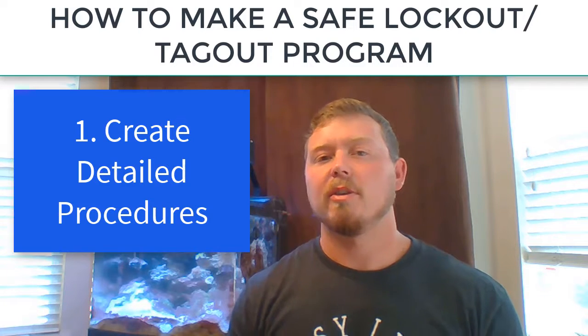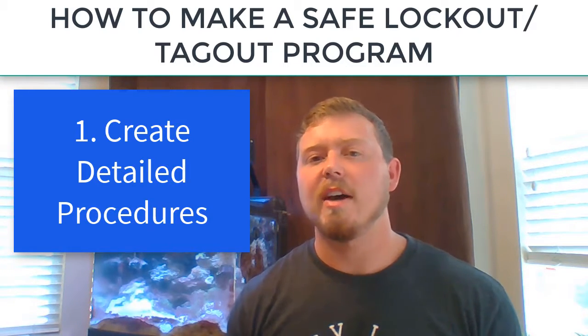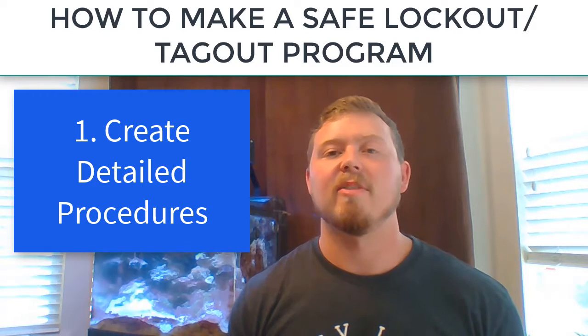Step 1. Create detailed lockout procedures. Identify the equipment that needs to be locked out and its location, and in my opinion, you should take a picture to help the employee identify it as well.